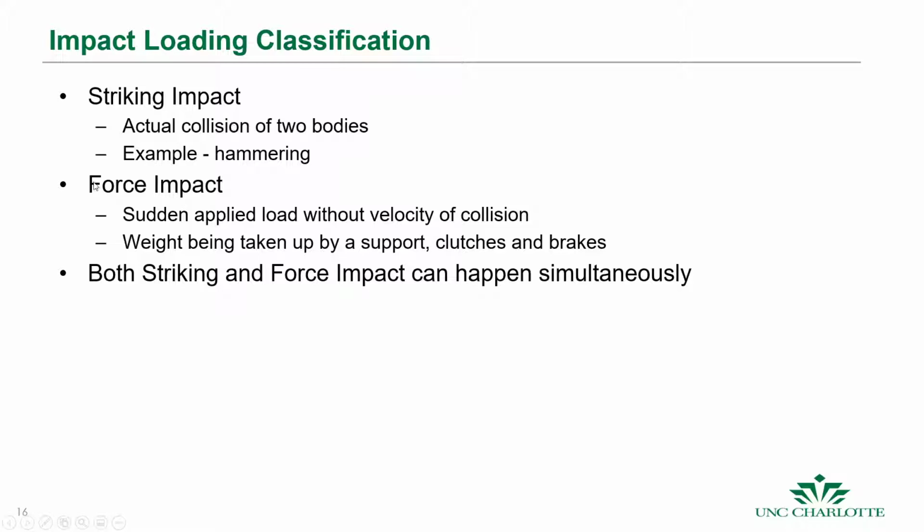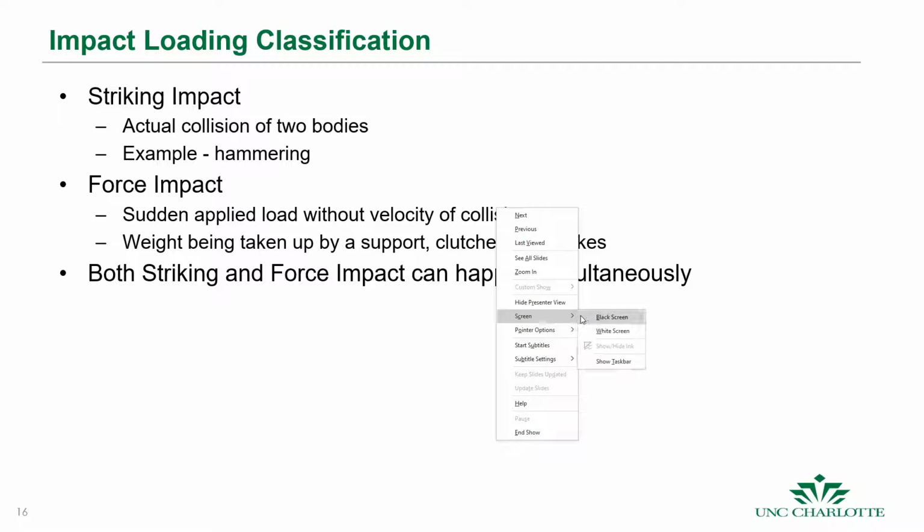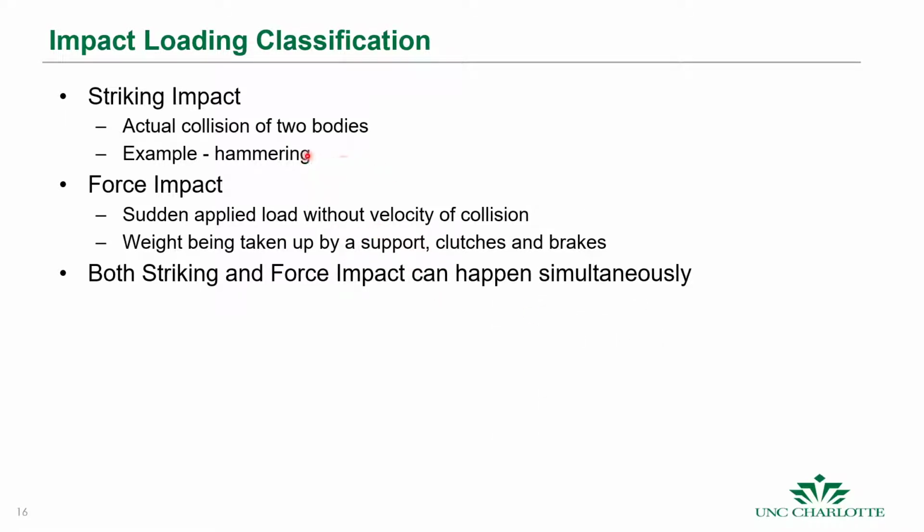Both striking impact and force impact can actually happen simultaneously, but that's how we classify them. Okay, so striking impact will involve velocity. Force impact doesn't involve the kinetic energy associated with velocity. It has more to do with going from a zero load to a non-zero load in a relatively short amount